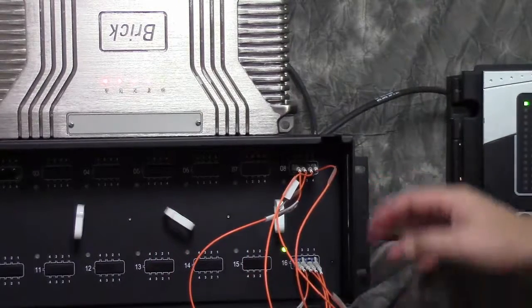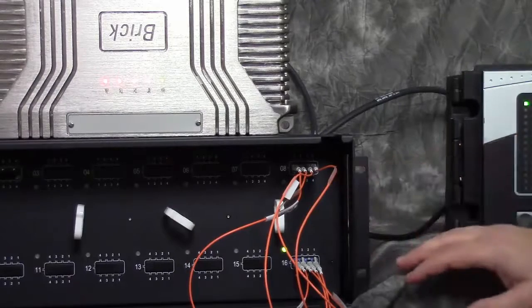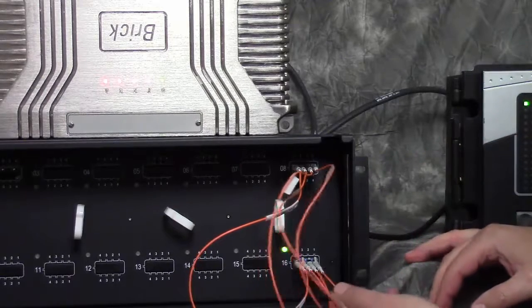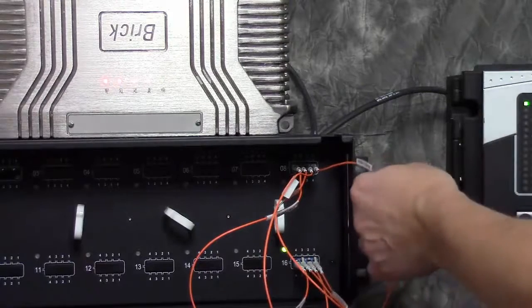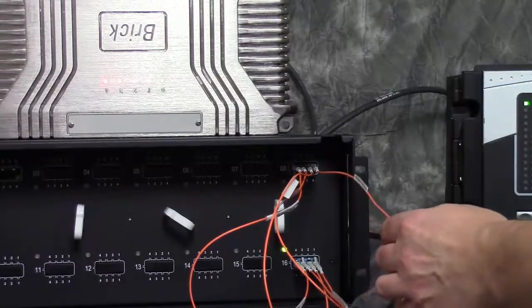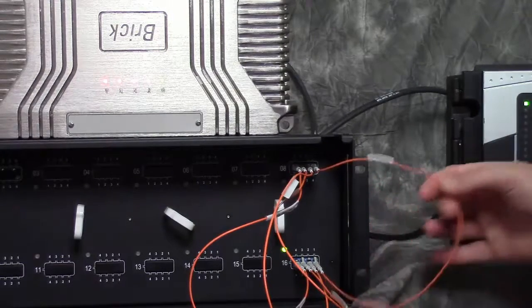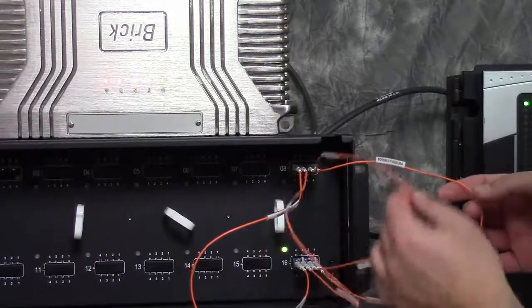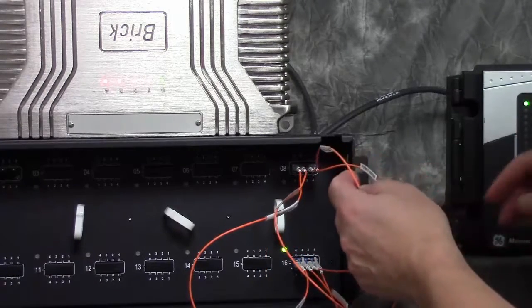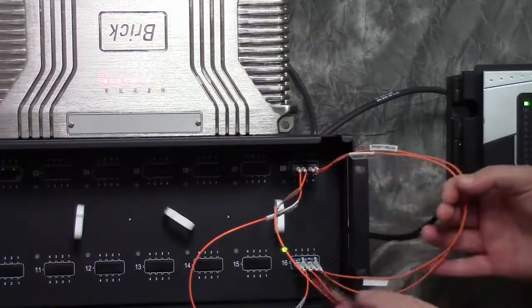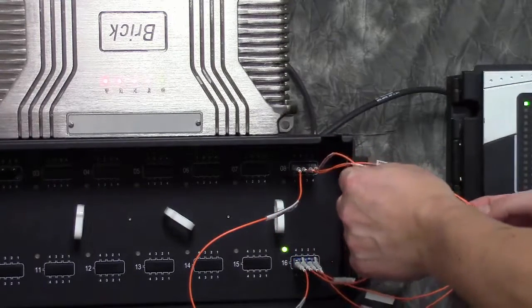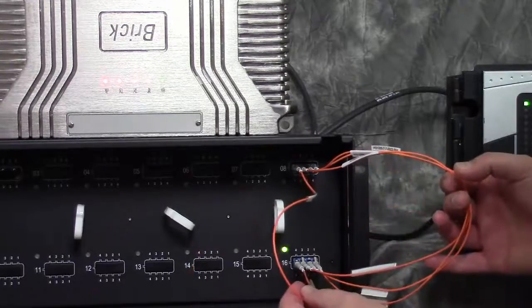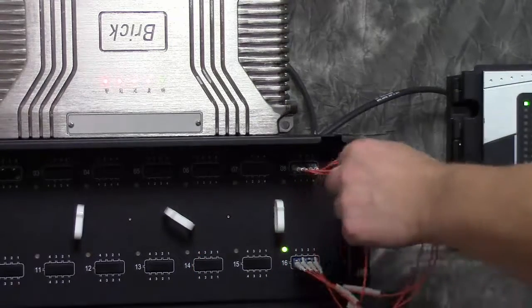Now, the numbers are reversed on the upper portion, so core number 1 is actually physically connected to channel 4 on the harness that goes to the UR. Core 2 is actually going to channel 3 in the universal relay. Core 3 is going to channel 2 on the UR, and core number 4 is connected to channel 1 in the UR.